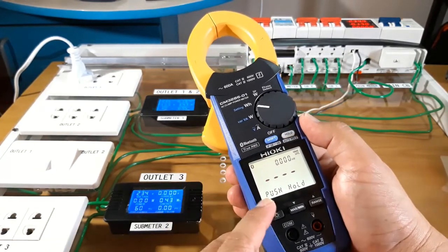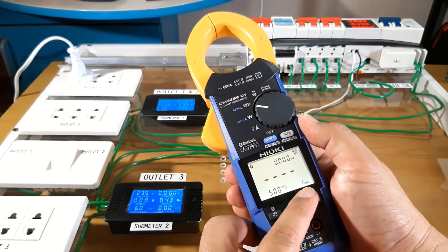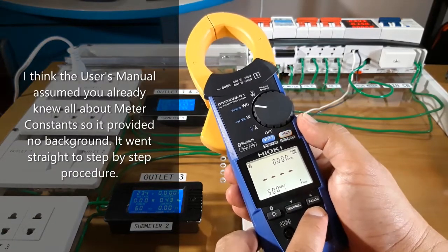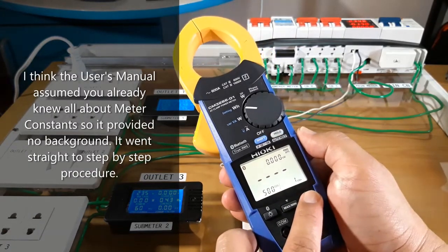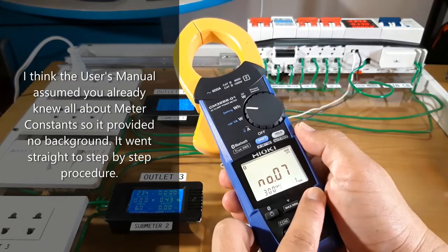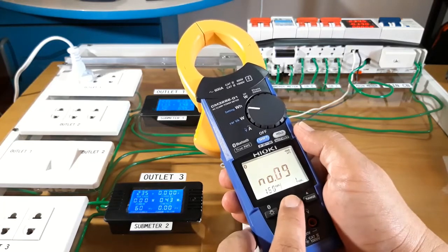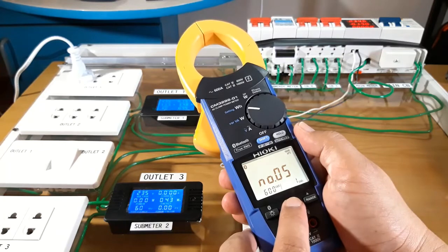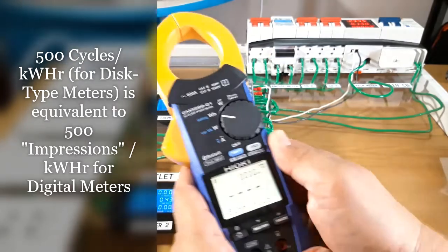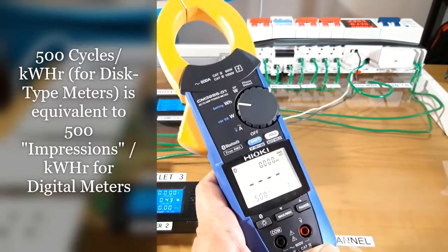But as you can see, at the bottom, there is the energy meter constant saying 500 cycles per kilowatt hour. This is the function that confused me before because I did not understand it at first. If we scroll to the menu, we can see that there are several choices of meter constants. But the one we're most interested in is the 500 cycles per kilowatt hour, because this is the meter constant that corresponds to the meter that we're going to use later on, whose meter constant is 500 impressions per kilowatt hour.